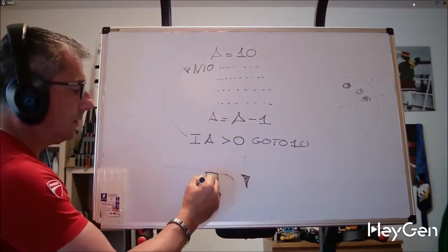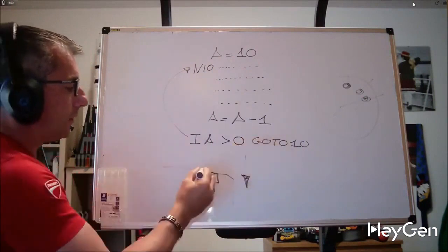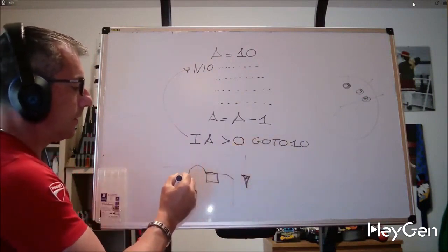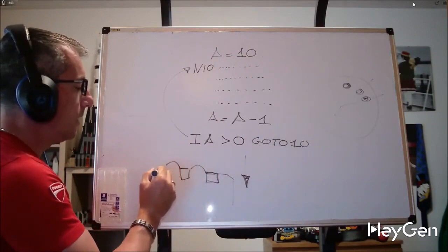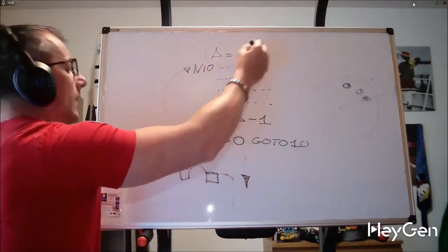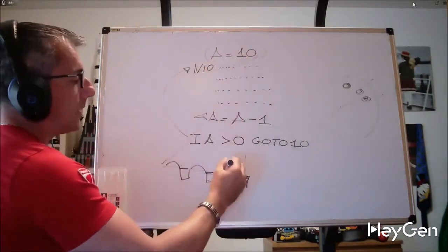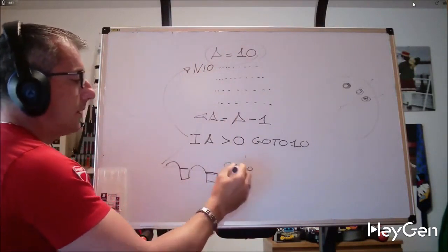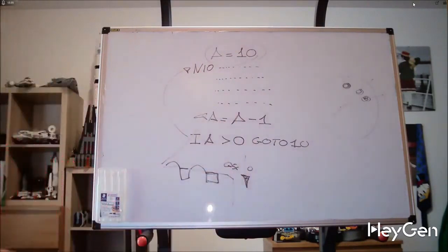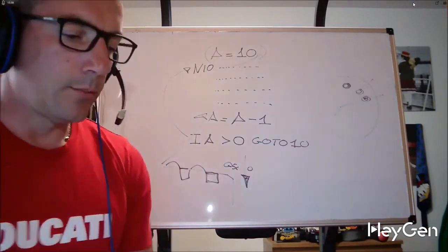I make a groove. I arrive here. I move the origin by 10 mm. I make another one. I arrive here. When I have counted the number of grooves equal to A, I leave. I set the origin back to 0, G52 0. And I continue with my little program.